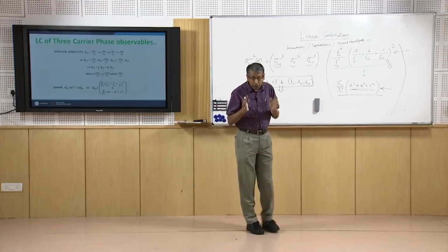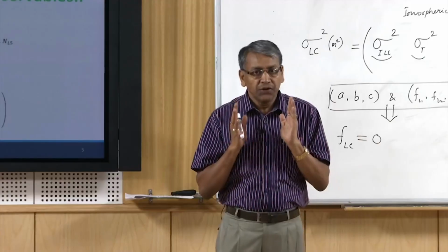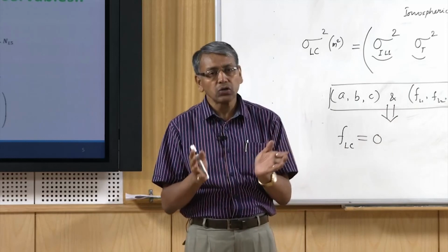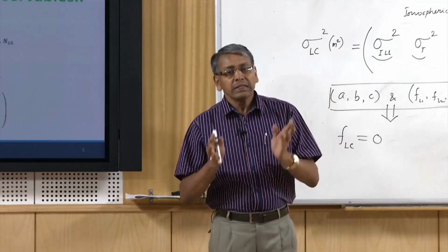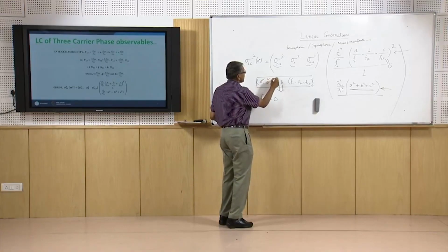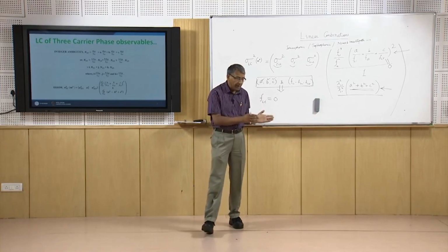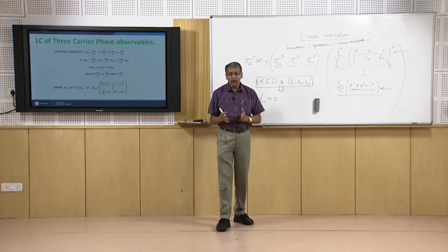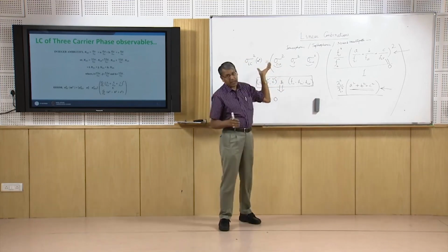Now as you know, the observables are different in different campaigns, so also the errors that will be associated with the GPS observables. Thus the constants A, B, C we take will also vary from campaign to campaign to arrive at a particular characteristic of the combined signal.